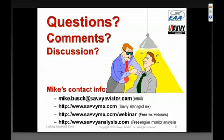I fly a turbocharged airplane that I regularly fly up in the flight levels where the OAT might be -20, but it's still above standard atmosphere, so I don't have to worry about it, because standard atmospheric temperature is very cold up there. So it's only if the OAT is significantly below ISA, International Standard Atmosphere temperature, that you need to worry about adjusting the target temperatures downward.